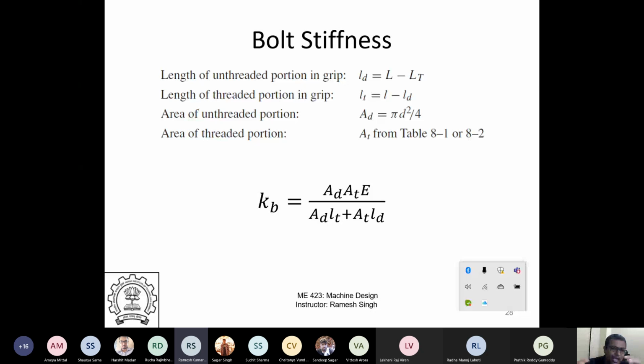In bolts, one side is passive. You are tightening only from one side. And in studs, you have the option to tighten from both the sides. So typically, studs are used in very stringent applications where you require a very high degree of tightening. Flanges in the process industry, some applications where you want very high stiffness and almost perfect contact between the mating surfaces. Okay, yes, sir. Thank you.